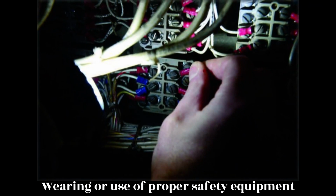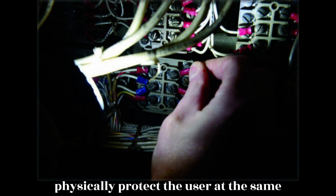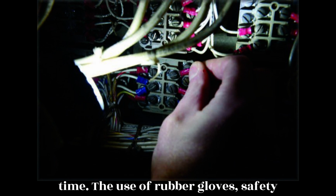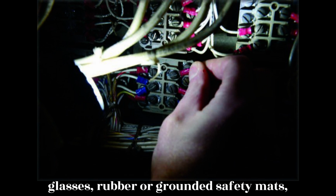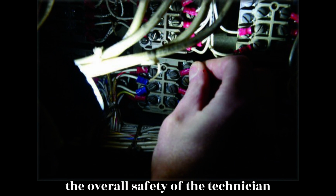Wearing or use of proper safety equipment can provide a psychological assurance and physically protect the user at the same time. The use of rubber gloves, safety glasses, rubber or grounded safety mats, and other safety equipment contributes to the overall safety of the technician working on or with electrical equipment.